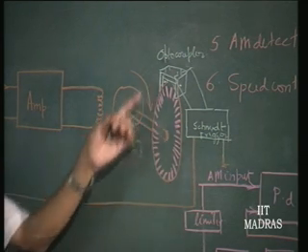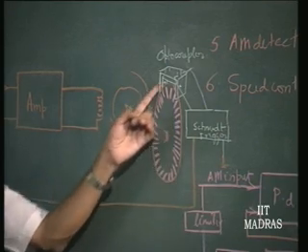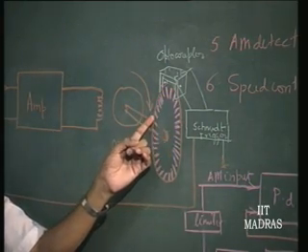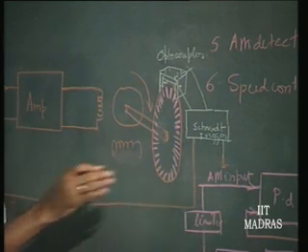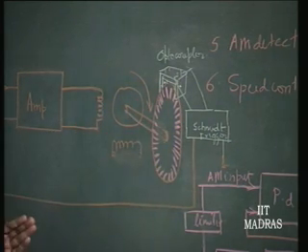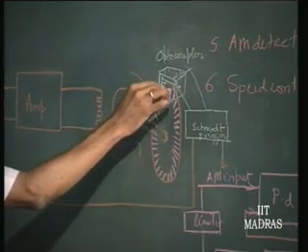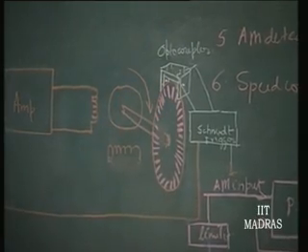This optical tacho is like this. On the shaft of the motor, a dial like this is put with slots in the circumference which are equidistant. So, on this dial you cut slots which are equidistant on the circumference of the dial.